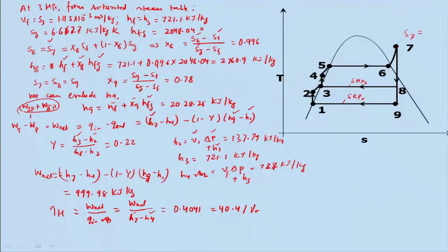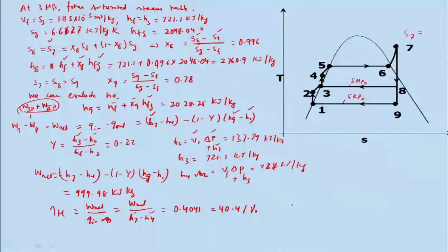So, by this way you can solve these problems, right, and look at it, and one can see that, compare with that, and then you will find out in this case if you take the same problem without regenerative, the thermal efficiency will be coming something 38.4 percentage. So, that means this is without regeneration, right. So, therefore, there is an increase in the thermal efficiency, but it need not always be true, that depends upon how you have designed and how it is being operated.